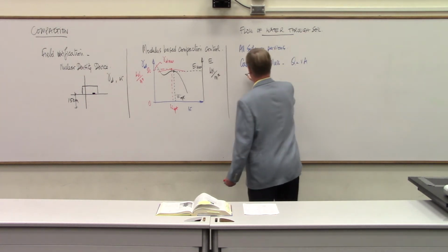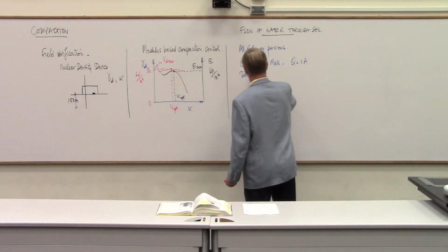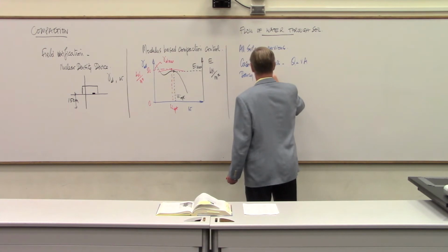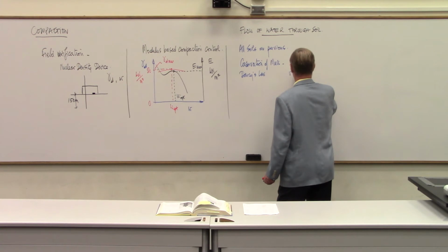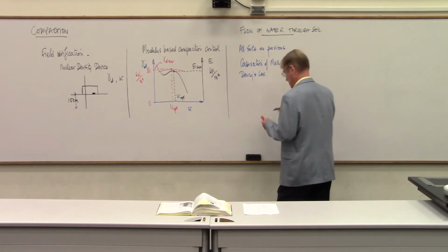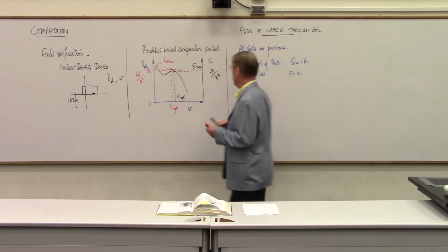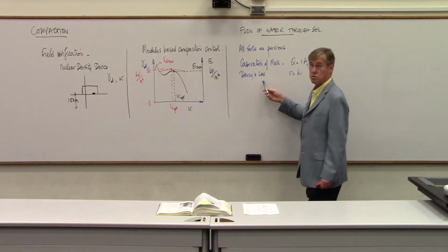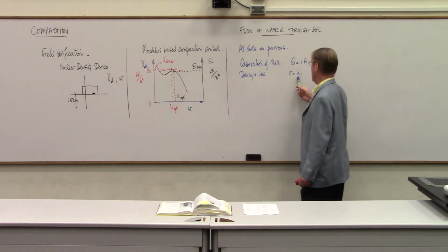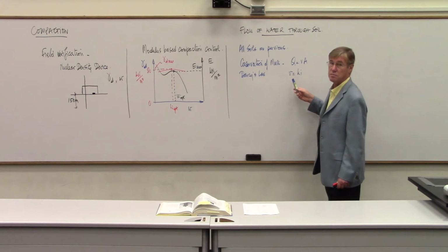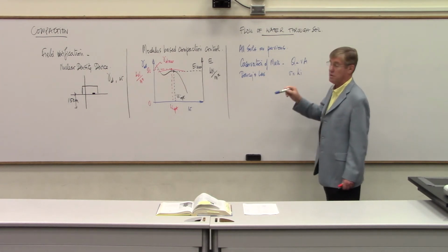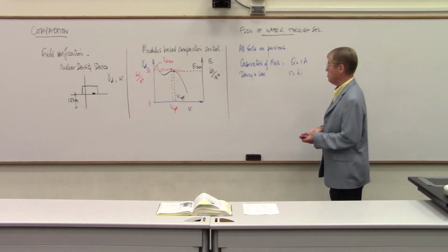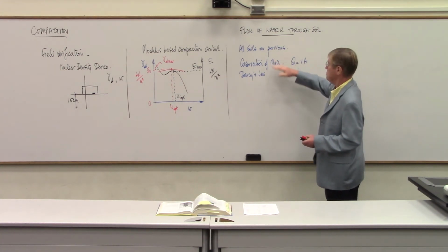The second one is Darcy's law. And this one is expressed by V equals Ki. This is a constitutive law because K is a soil property. In Q equals VA, there's no soil properties. It's whatever comes in has to go out. So I'm going to discuss those one by one.